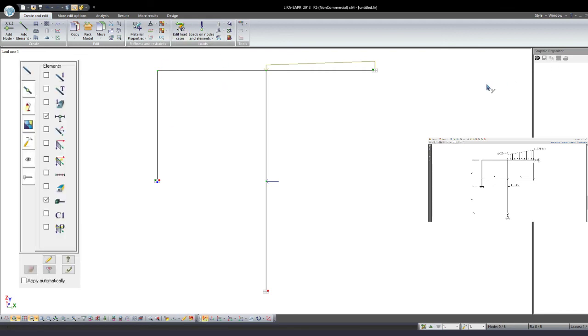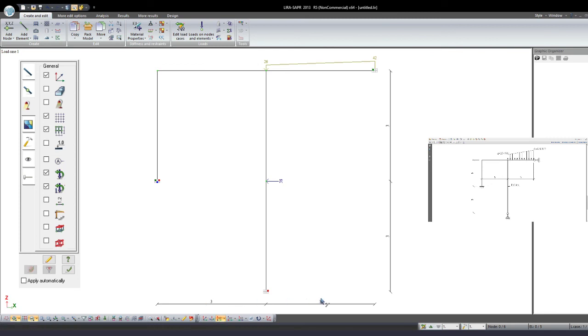We go to flags on drawers. The first we choose is load magnitudes and dimensions on projection. I touch redraw, and after this in the down panel touch XZ projection. You can see when I touch this I can see dimensions. Did I create it correctly or not? And you can see yes, it's correct.